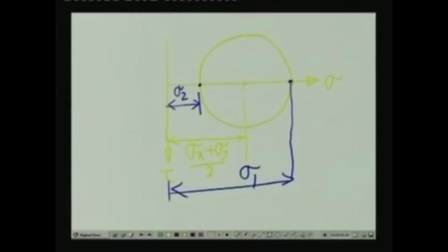If you note that in these two planes where the maximum and the minimum normal stress act, the values of the shear stresses are 0. So, the planes where the maximum normal stress acts, the values of the shear stresses are 0, and these planes we call principal planes, as we have seen in other lessons.